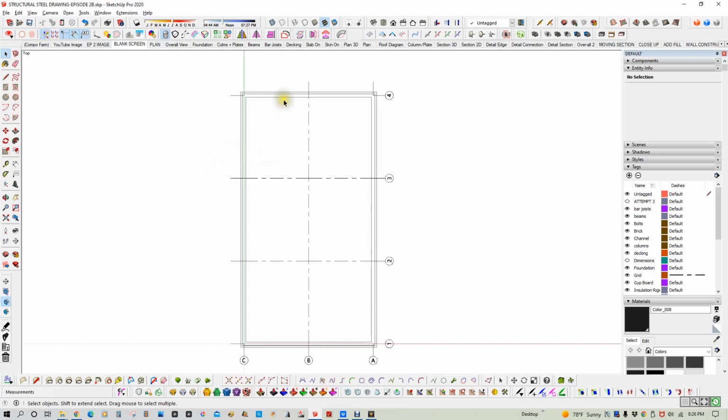Before we're done, I want to make a scene, and it's already here, called Plan. I'm going to right click on this and update it so that this particular setup is saved in a scene. Sorry, it's getting late. So I can go back to it at any point in time. So to fix this as part of that scene, I right click on the scene tab and pick update. Anytime you correct something that's part of a scene, make sure you pick update, because it's frustrating to some people that get to the point where they think they've updated the scene by drawing stuff.